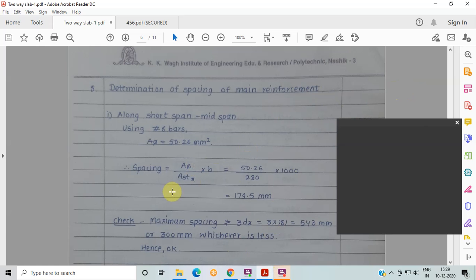So let's calculate the shear carrying capacity of the reinforced concrete section, that is Vuc. Vuc is given by K into tau c into bd. D is again the small d. When you are doing this check along X direction, obviously we have to provide d for X direction. That value is coming as 58.128 kilonewton. Since Vuc is greater than Vu max, it is safe.